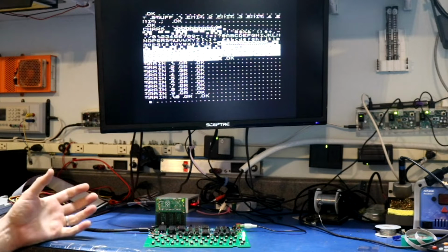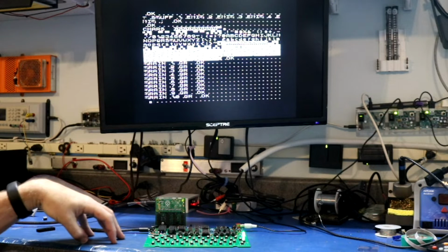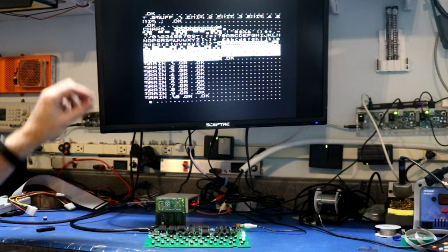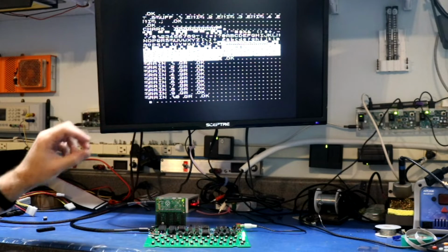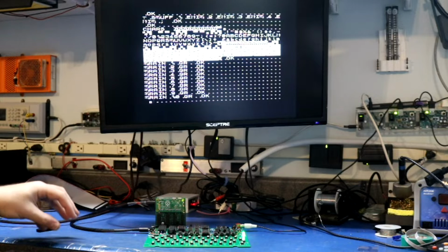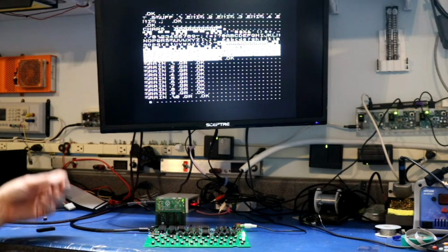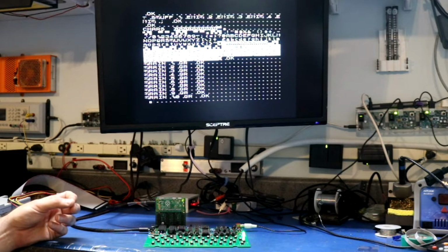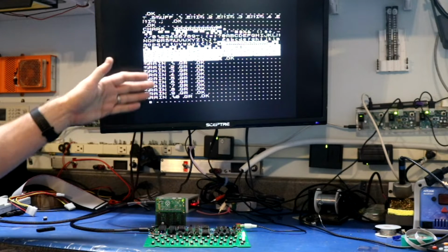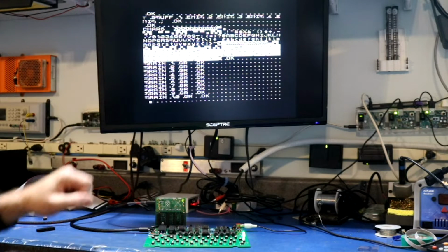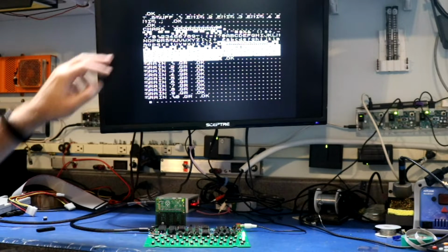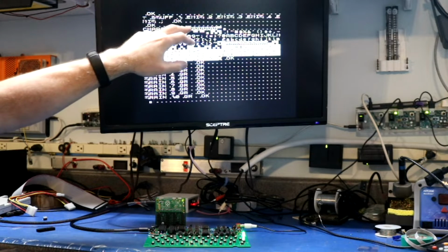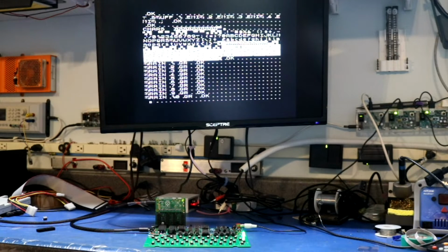The Jupiter is kind of cool in that the character generator, the thing that turns values in video RAM into pixels on screen, is in normal RAM, and you can just write it. And you can redefine any character to look like anything else. So this tried to define characters 1 through 10 to be this train symbol. And it did that. Characters 1 through 10 did pop up and change like they should have.